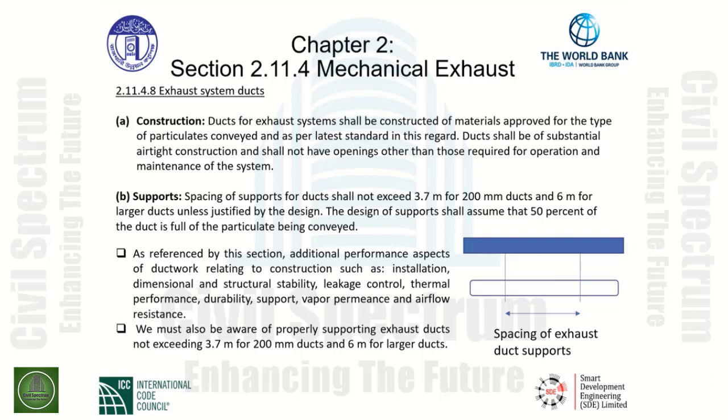As seen here on the right hand side, the graphic, proper support is required and we are given a maximum spacing interval according to this particular section. So as inspectors out in the field, we must verify that the ducts have been constructed of approved materials as designed and the spacing of supports do not exceed the maximum intervals provided in this particular section.